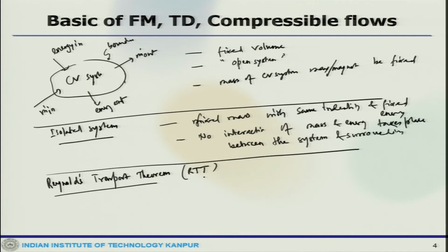A study of fluid in the Eulerian approach always requires some mathematical modeling of the control volume, either in differential form or integral form. So, the statements of the principles of conservation of mass, momentum, and energy with reference to a control volume are quite necessary. This can be derived by invoking RTT.